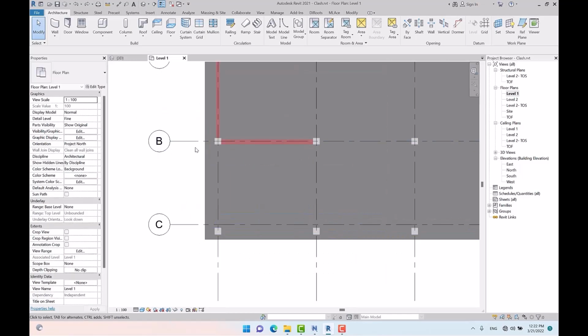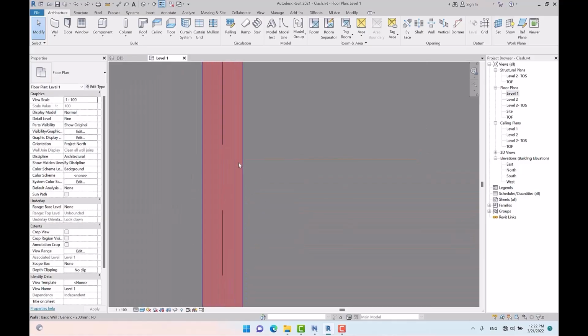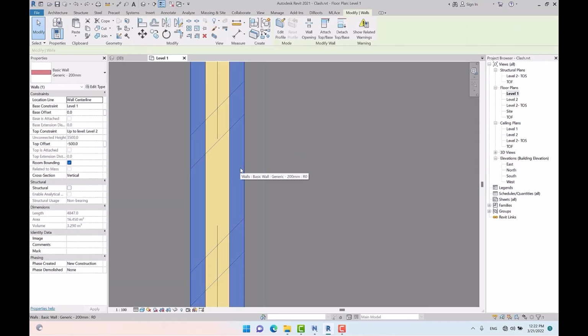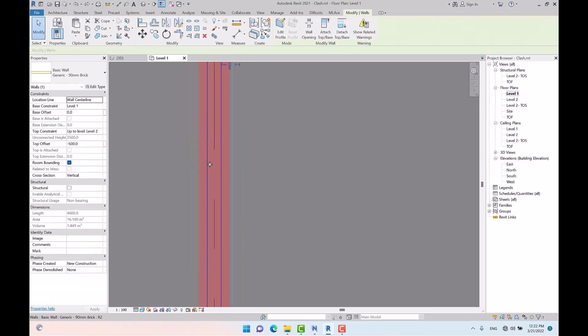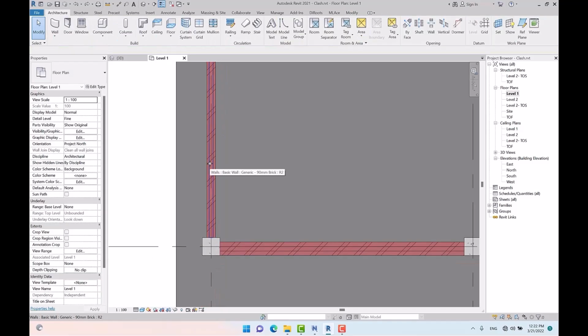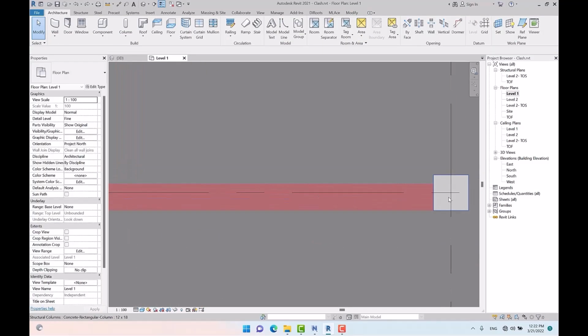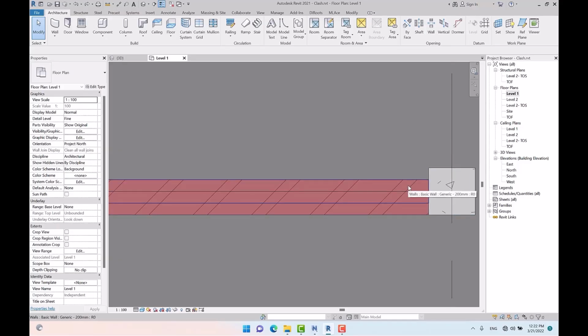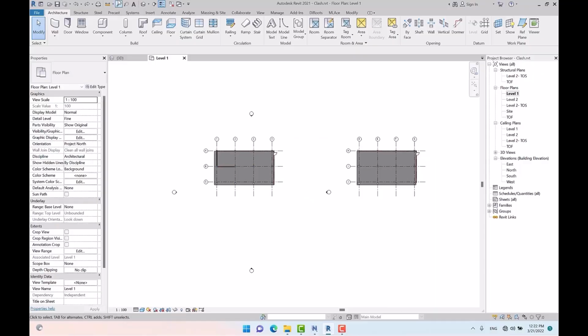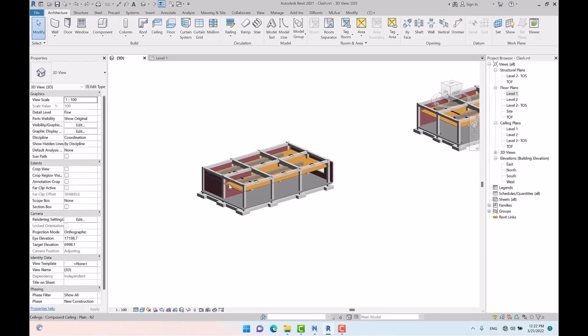But in the other model geometry, let me open the plan view. Here we got two types of wall, one of them is thicker than the other, and the thinner one is located inside the thicker wall, which is not correct, it's repetition. And on the other side, as you can see, we got a wall here as I'm showing, and on the other side I have added another wall, and this is not correct too. So I have prepared an intersection in the thickness of the wall intentionally.